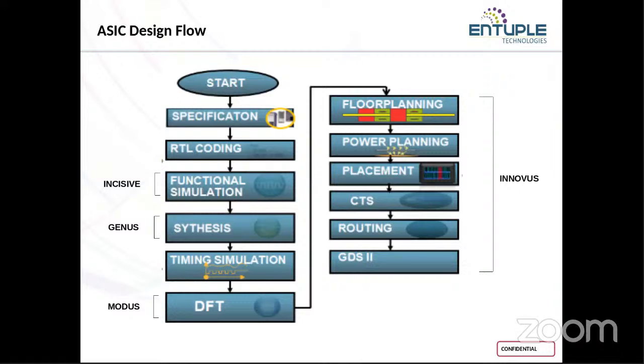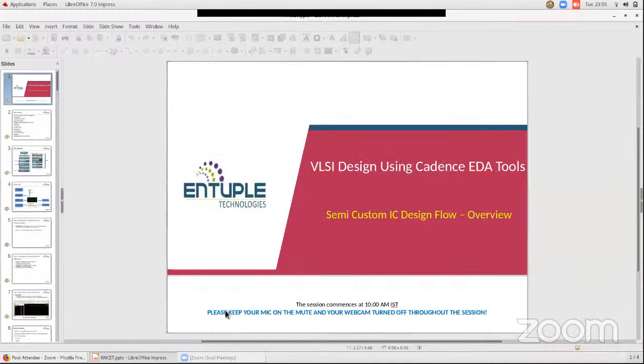While we are going through the physical implementation, we will discuss in detail what the floor planning is, what happens in the floor planning, and why we need to do it. All the details we will discuss when we get to the physical implementation stage. So now you can write your RTL code of your memory design, and you will perform the process in the semi-custom IC design flow. One after another, first we'll take a functional simulation, then we'll go with the synthesis, then the DFT, and then the physical implementation of your design. We'll be seeing them one by one in detail.